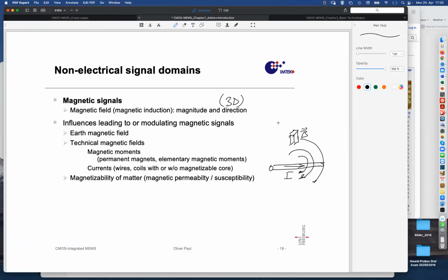I drew here a schematic Hall sensor. If we measure the field at a distance of this wire, we know what current flows through the wire. We have a non-contacting current sensor. Interesting. So the Hall sensors that I showed before are used to measure power dissipation by systems without intruding on them by making a direct measurement. This magnetic field comes for free.